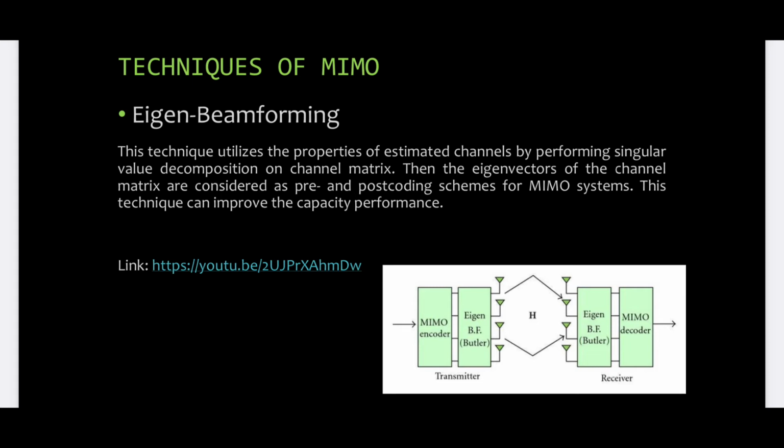So despite phased array having a seemingly advanced air to it due to its use in extremely expensive military systems, it is actually a simpler form of beamforming that can be done with a modern MIMO system. Phased array systems perform their beamforming using limited capability of phase shifting and combining of signals in the analog domain, which has some significant drawbacks, including the fact that the performance benefit degrades as the channel bandwidth is increased, and it generally works only in pure line of sight or LOS situations in the absence of any scatterers or multipath,